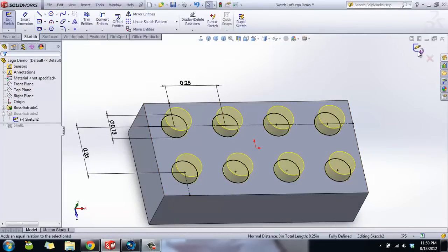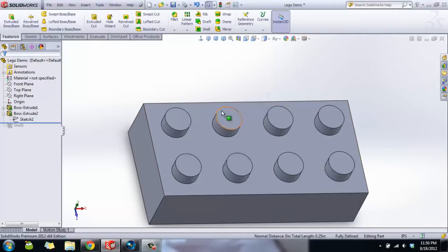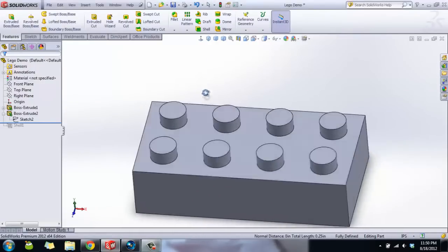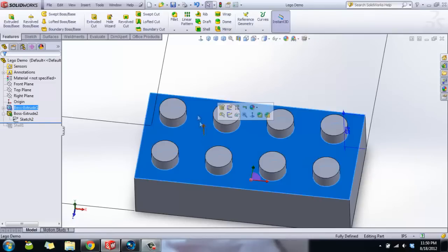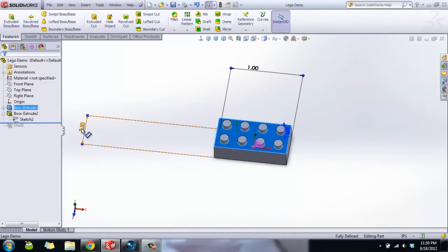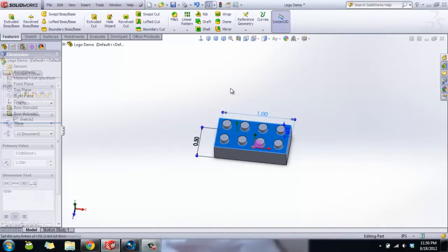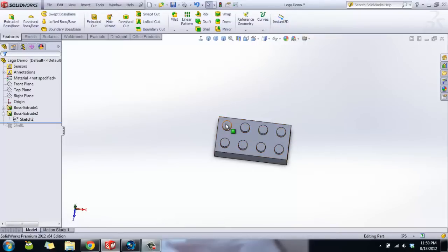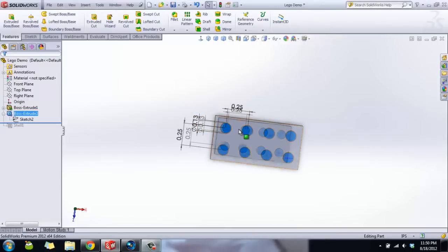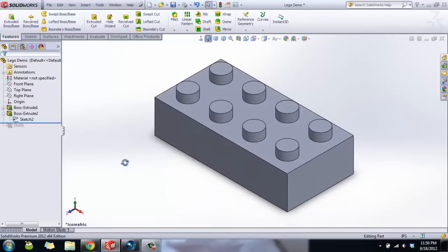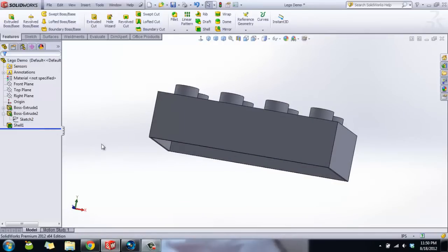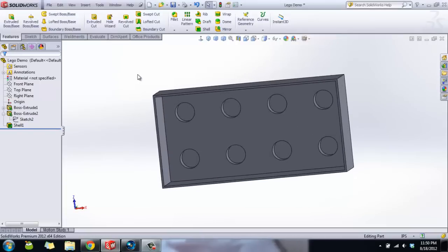We're going to click OK. This is the Exit Sketch button. It'll apply the changes. Now these things are evenly spaced, which will make them more useful in our later models. We're going to save our work. Here's the sketch again. So bring these dimensions in. And you can see how they're spaced here. Now we're going to put the shell back on. A little bit better spaced.